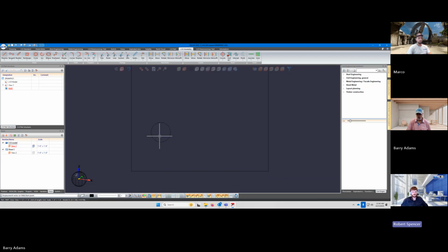If you hover near the circle in a certain way, you'll get the Z. The Z means center point. So you notice how when the Z lights up, you're selecting center. If you move the cursor a little bit further away from the center, you'll get a tangent or a quad point or something different perhaps. Quadrant, yeah. So Z equals center.